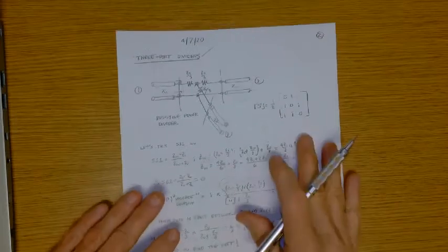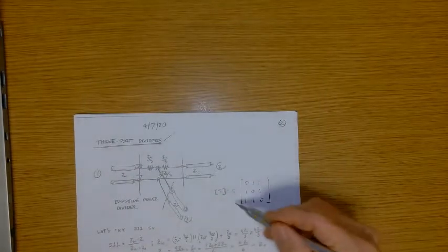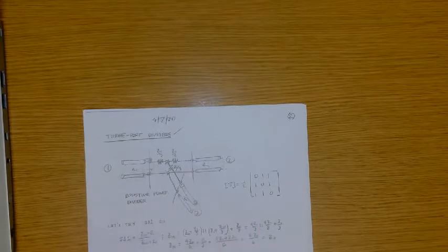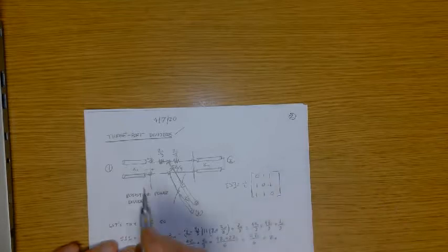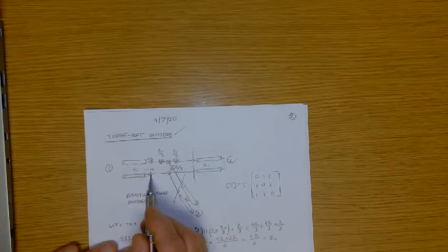And so this shows the scattering matrix for this particular microwave device, this resistive power divider. So S11 is 0. We should be able to show that, and we will momentarily, meaning that none of the input wave is reflected at this port.